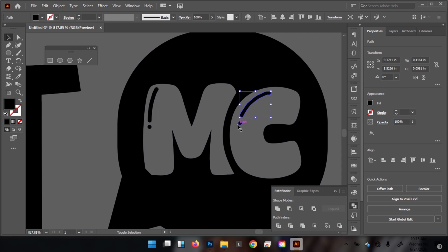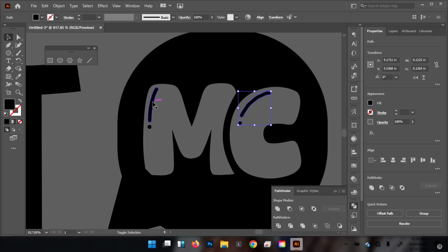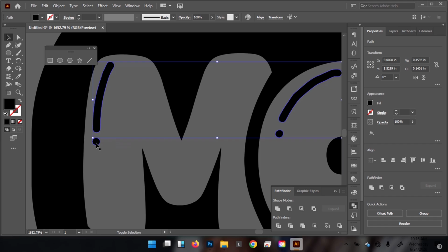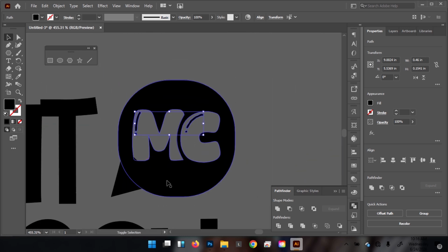Select these ones. So you just left click on it, add shift, select the other, left shift press down, add this, shift press down, add this as well. If it is proving problematic, with shift pressed down, add control and space, and then zoom in so that you can get this particular object. After zooming in, release the control and space, and with shift pressed down, add this object. And right now add this one too as well with shift still pressed down.